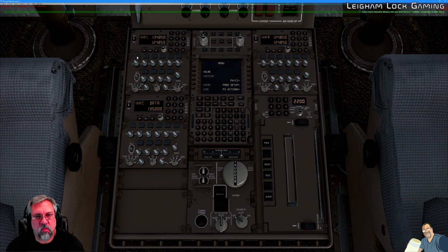Visibility. Now I go back down to the audio control and turn it off because honestly I don't want to hear air traffic control. We're not going to be flying with air traffic control today, but I did need to be able to hear the ATIS report. And what that told me is that our barometric pressure is 30.21, and that runway 30 is the active runway in use.